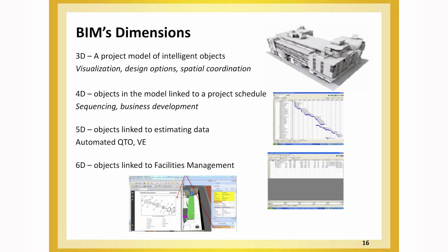And how we can apply this in real life and have life cycle management, and even go further into security operations incorporation and event modeling and all that. One of the projects we're working on, they require us to have level of design like 300, 400, because then the maintenance will use something like Maximo and have all the data pulled in, so all that data that you design, so a VAV box has the manufacturer model, service type, filter size. They use that for maintenance, so they don't have to recreate it.